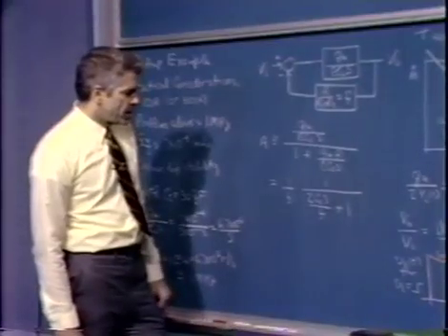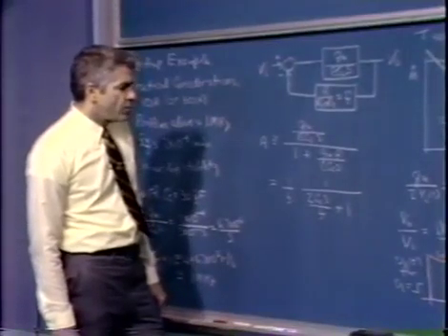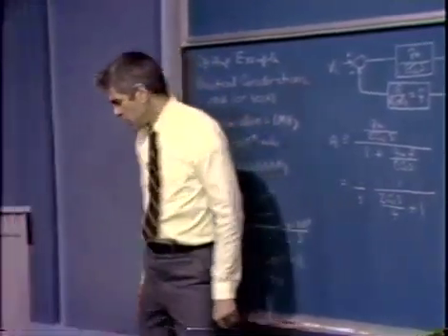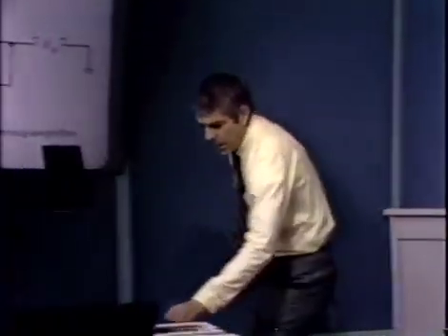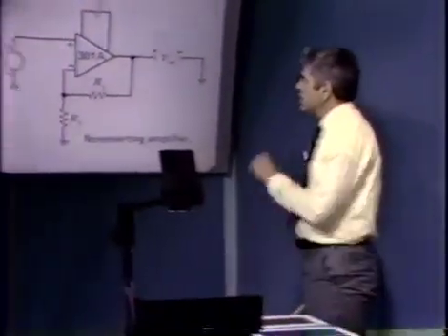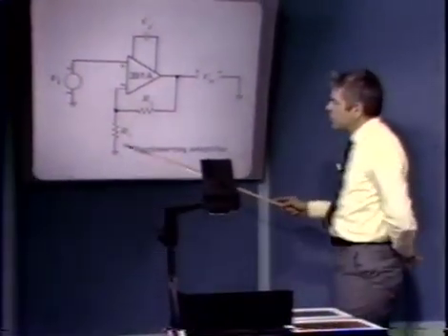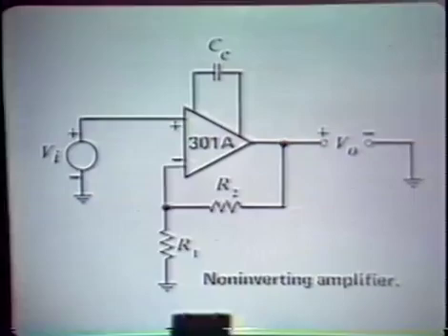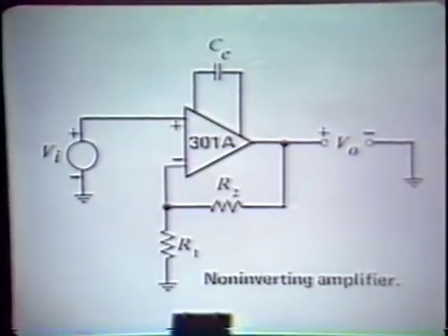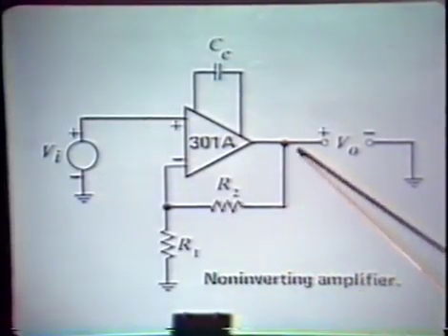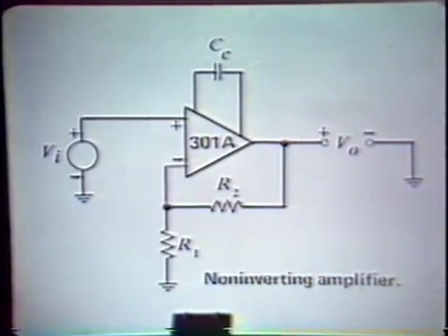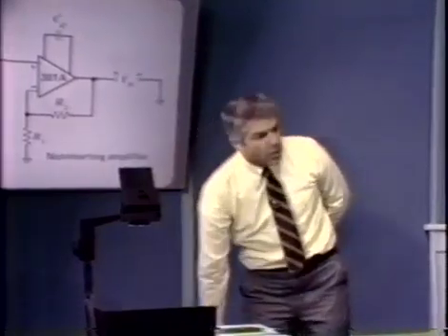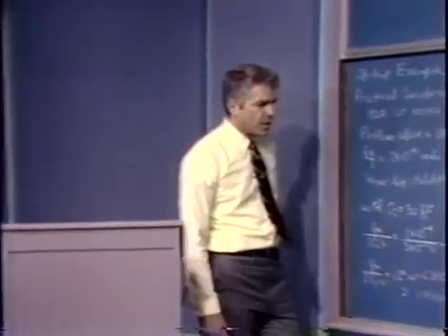Now, the problem is that as we go to larger and larger closed loop gains, in other words, if we go back to our original amplifier, in order to get higher closed loop gains, of course, we'd make R1 smaller relative to R2, thereby lowering F. And since the ideal closed loop gain for this non-inverting configuration is simply 1 over F, as we lower that ratio, we make F smaller, we get progressively higher closed loop gains.